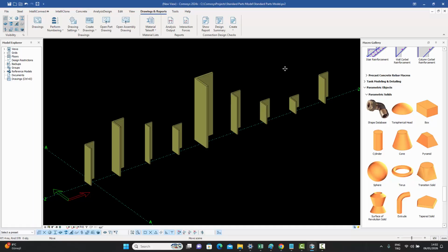Now, this requires a special numbering process. The software should know what standard parts are available in the inventory, and then in the full model, whenever the exact same geometry is used, instead of giving it its own number in that model, it should give it the same number as the standard part's number in the inventory.